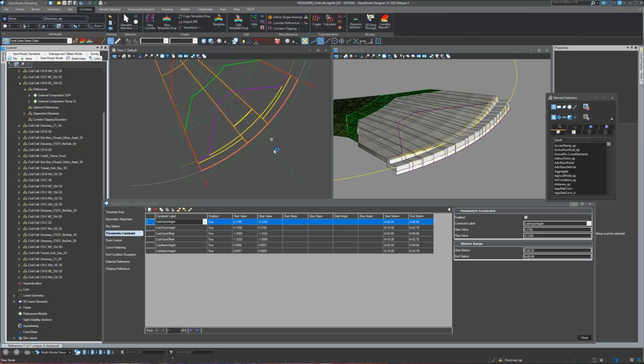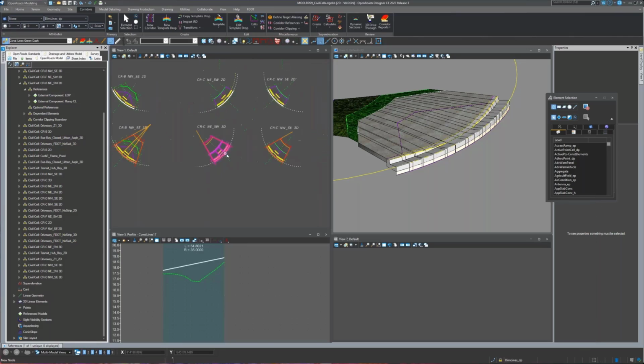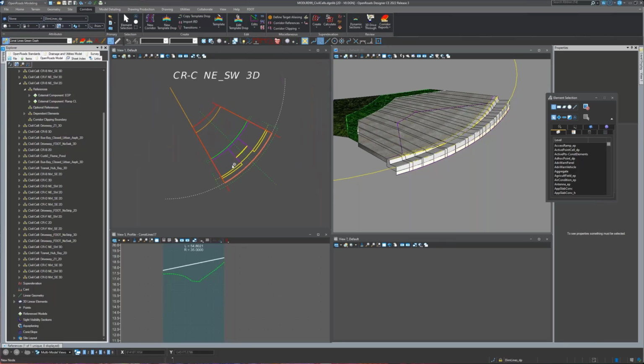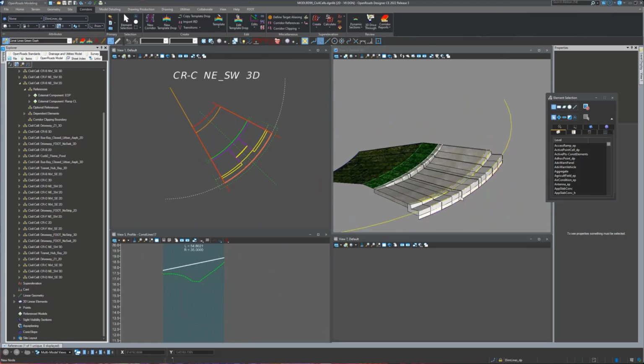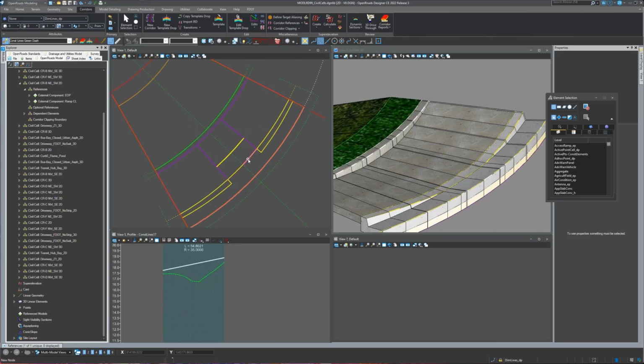So that's the, what is this, CRB. That one I do have 2 different templates. But if I come over to the CRC, this one I only have 1 template. So if we slide over, because I know when I get down to here, this landing is going to be 2%. So when I go from here to here, that's going to be 2% for sure, always.